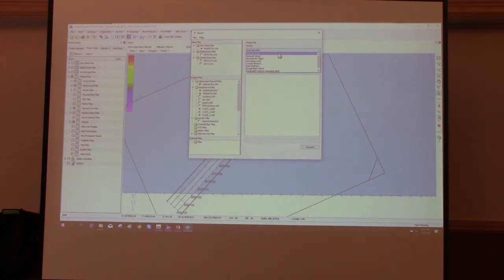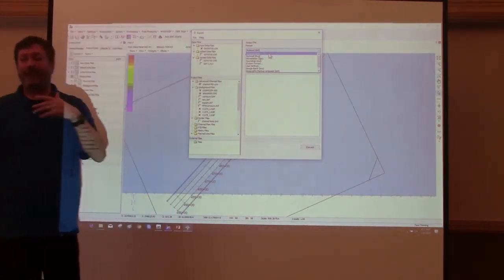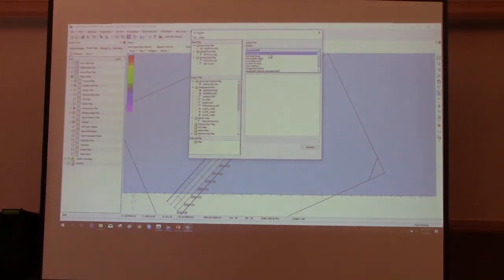So we've got your AutoCAD, DXF, DWG, DGN, XYZ data, different flavors of the XYZ data, whether you want XYZ, XYZ with a record number, invert the Z value, or you might want YXZ, for, I think some programs prefer northing easting instead of easting northing.